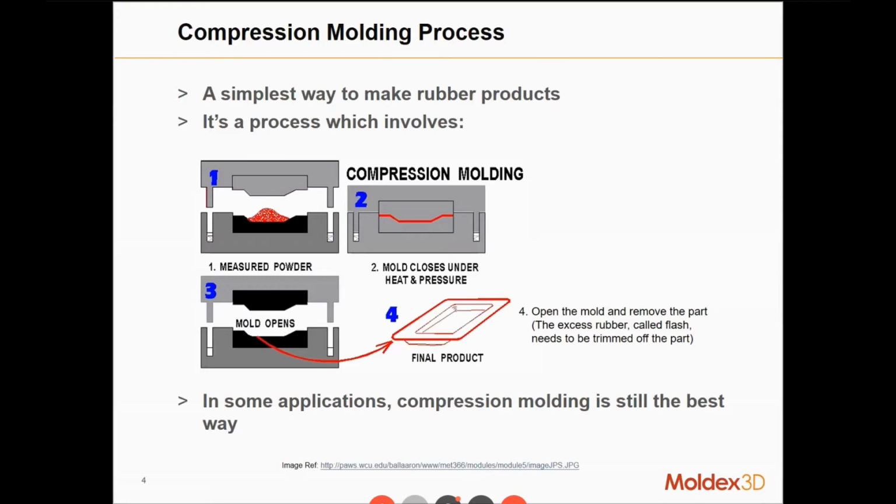And this process is like we put either it's a powder or it can be a sheet molding compound or in other forms. Either way, we put the charge in the mold, and then it will be the mold closing, which is the compression stage, and we'll form the part. And after that, we let the polymer go through a packing stage or a curing stage. And after that, is the mold open and take the part out. We get the final product.